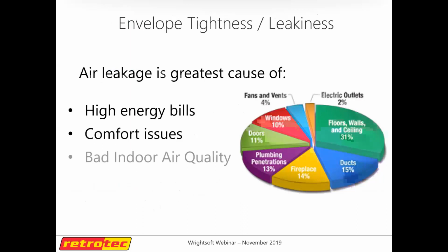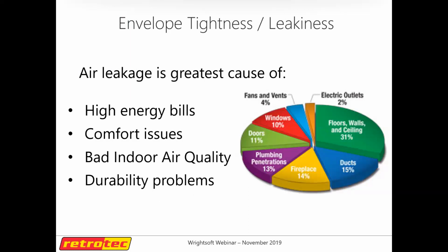I wanted to go to the effects of air tightness as well. I know this is kind of a brand new concept for a lot of HVAC guys. A lot of them are really just looking at the equipment that they install, and that's about it. They don't really think about the actual building that it's in. One thing that our friend Joe Madosh used to always ask is, what is the largest duct system in a building? And his answer would be the envelope. It's that defining point between inside and outside. Unfortunately, a lot of HVAC contractors don't think to look at that, when it can actually make up a large percentage of the load.